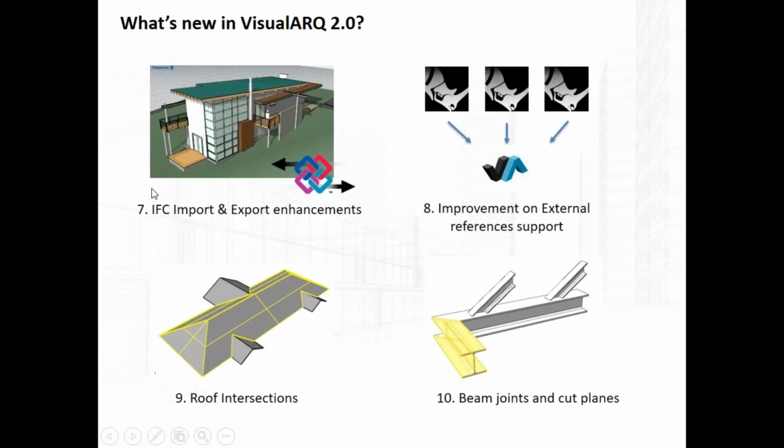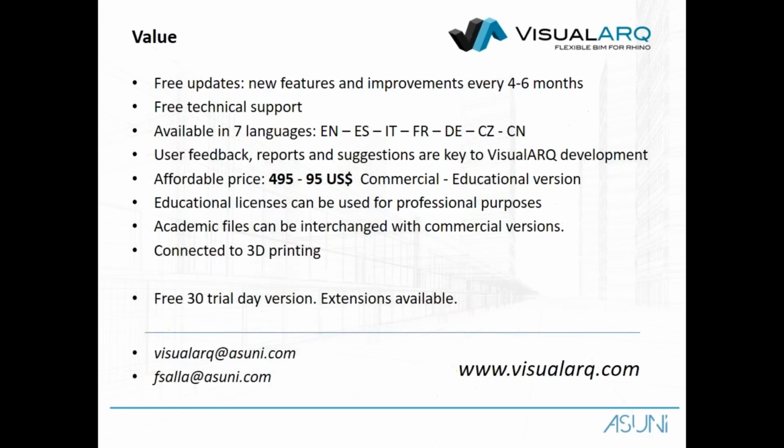And more stuff we have added in the new version is more enhancements in relation to the IFC import and export. We now export colors or materials. We will support external references, and groups will calculate the intersections among them. And we have also added the option to calculate the intersections of beams, as well as controlling the beam cut planes at the ends.